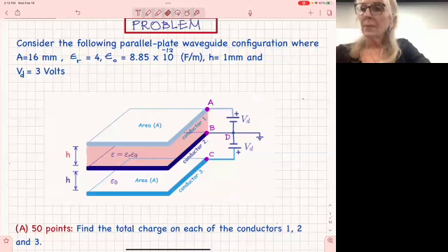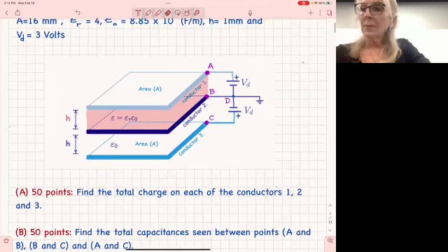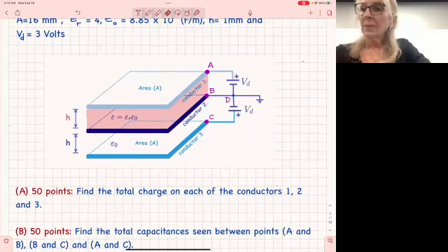The moment, however, I turn it on, a lot of the metals go to different potentials. And if they have different potentials, then there is capacitance between them. And if there is capacitance between them, then they have crosstalk, as we say. What is the crosstalk? Exactly the way I will explain it here. Okay, so let's see what happens when the metals talk to each other, as they say.